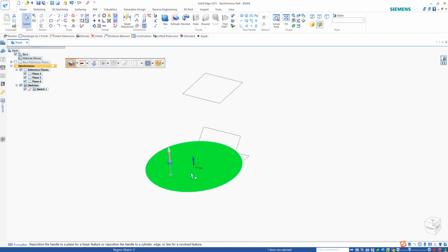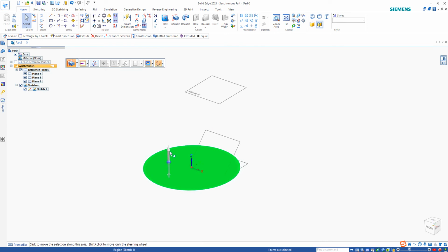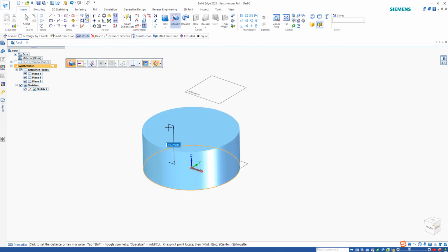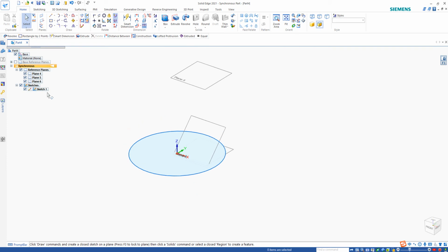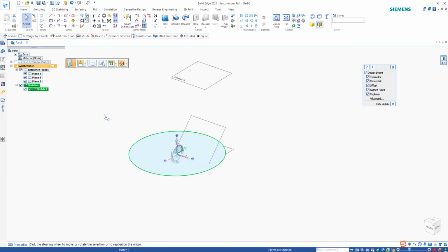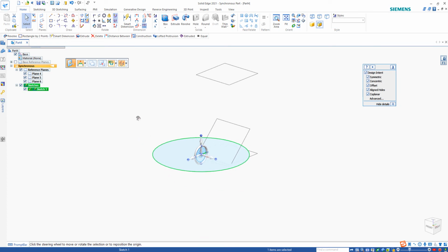If you only click the sketch, it won't appear. Although you can do the pulling options as we introduced before, you're not able to move these sketches. So to move the sketches, you need to go to the model tree and click the sketch. This is very important.